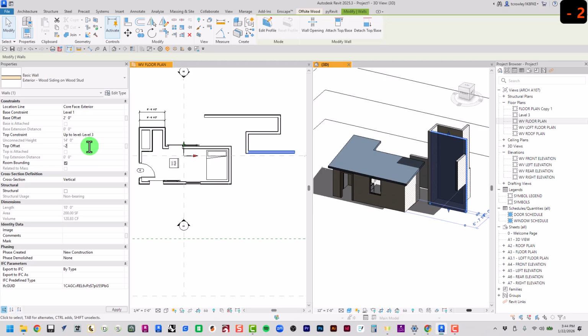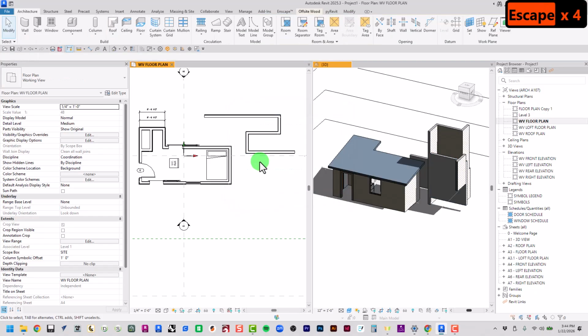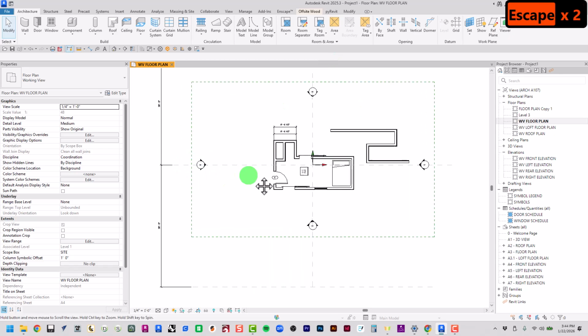So with that, I'm going to go ahead and get started on drafting this floor plan in front of me. When you receive this template file, you can go ahead and delete all of my work right here. Delete all those walls. Check it in 3D. Make sure you've deleted everything else, such as this roof, this floating wall that's far above that cutting plane, right? I wasn't able to see it in the floor plan drawing, so if I bring that back, Control-Z to undo, right? It's here in the 3D model.